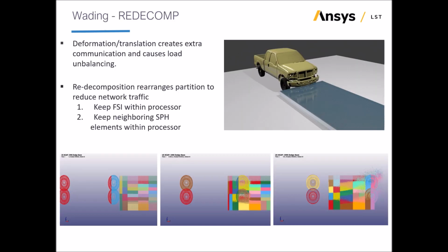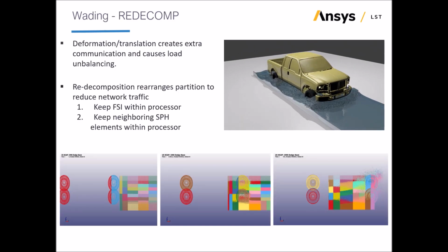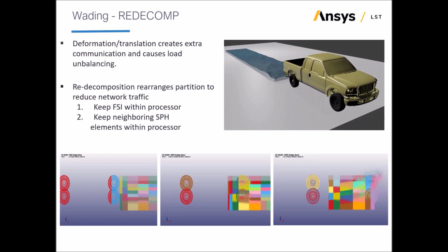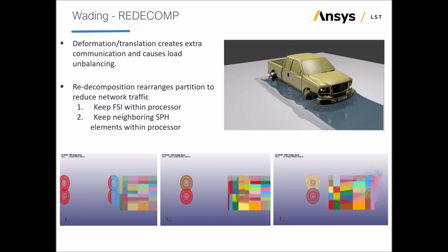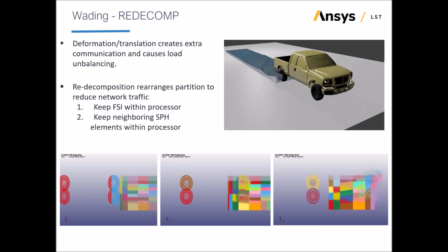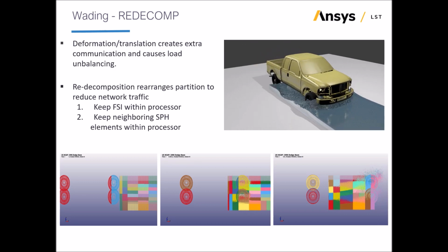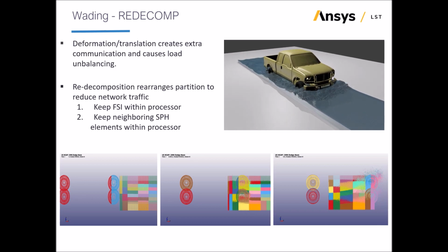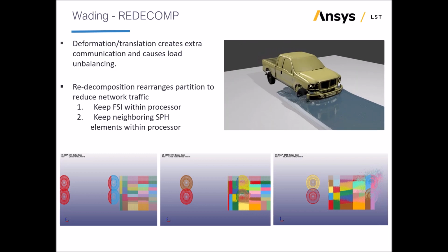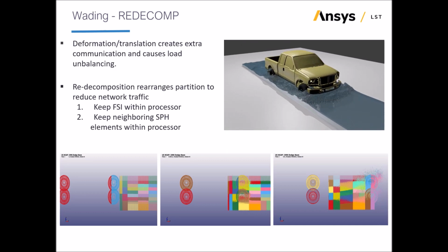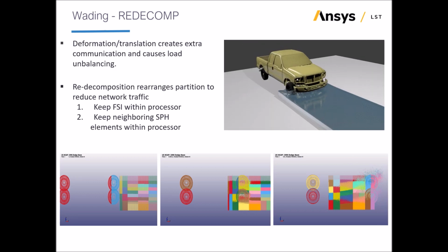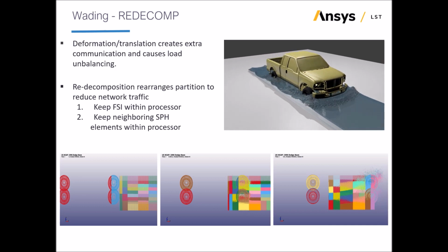You can now tell LS-DYNA to stop the analysis, make a new decomposition optimized to the current condition of the model, and continue from where it left off. This is called re-decomposition. Now, to do this, LS-DYNA has to write out a massive file to restart from, wash out all its memory tanks, and read the file back in, so there is an overhead there, and you wouldn't want to do this too often during a simulation. However, if you are running the type of analysis that becomes very much less efficient as it progresses, this may be worth considering.